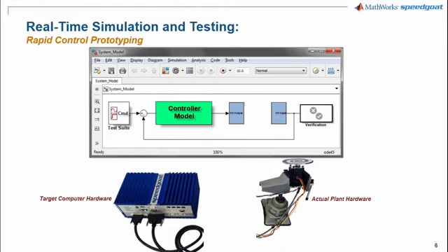During this process, the code generator will generate code from the entire model, test vectors, controller algorithm, I/O blocks, and verification checks. It'll then initiate the compile and linking specific to our real-time simulation and testing environment. Once that has finished, it will download the resulting real-time application onto the target computer hardware, which is running a commercial-grade, optimized real-time kernel.